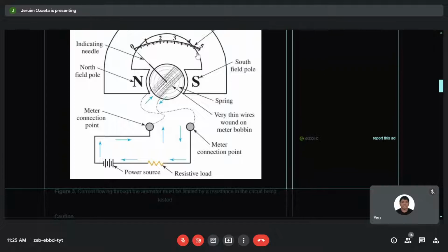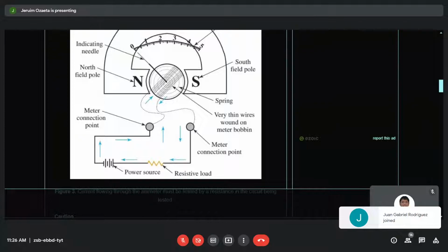Even in the design of digital instrument circuits, this is still the same consideration, except that in the digital instrument there is no more magnet necessary. All there is are the quantizing of the magnitude, converted into a digital value and then reconverted to a numerical value to be displayed. Okay, so take note, the moving coil has a definite value of allowable current.